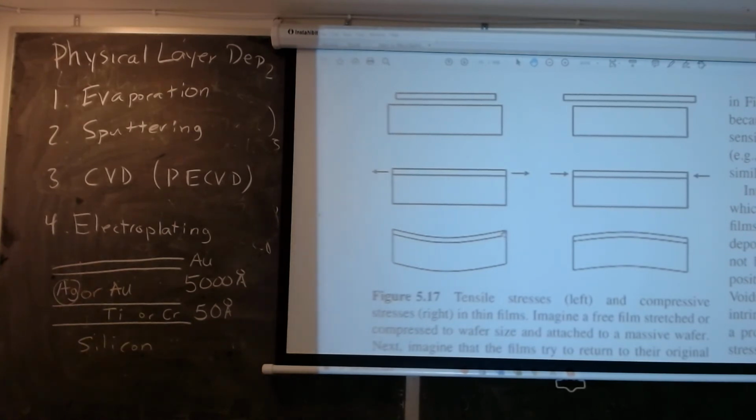You kind of have to put it under the microscope and observe that when you lay it on the platen, the sides are up higher than the bottom, which you can see with a depth of focus type experiment. There are also instruments in the laboratory that allow you to image such a bowing. Well, a bowing of 10 microns is a lot of bowing.